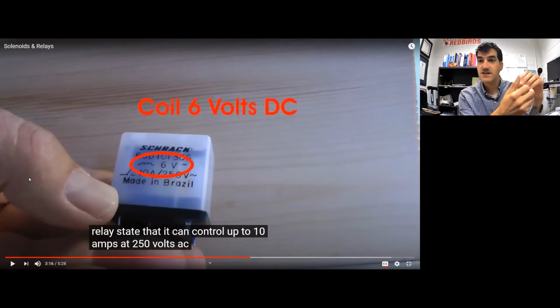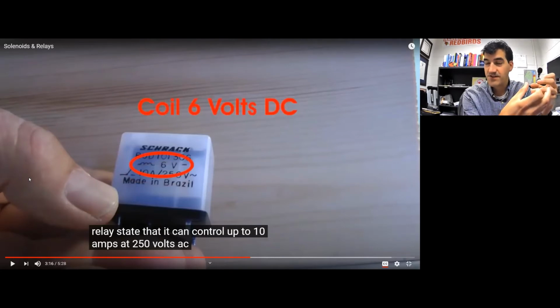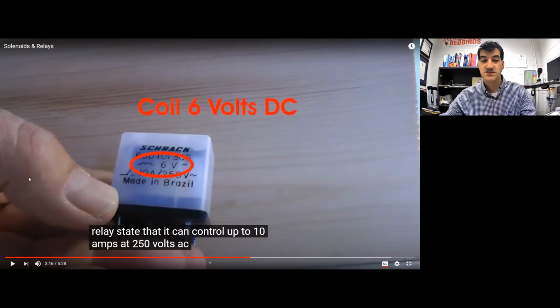The second part is that motion, what it's going to do for us in a relay is move a switch. Now, one way to move a switch is just by using your hand. You come into a room and you flip a switch. But another way to move a switch is by using a relay, where the solenoid is going to cause the movement of that plunger, and that plunger's movement will change the position of a switch. All right, so a relay is nothing more than a solenoid connected to a switch. And we just talked about different kinds of switches, and we can use those different kinds of switches in a relay.